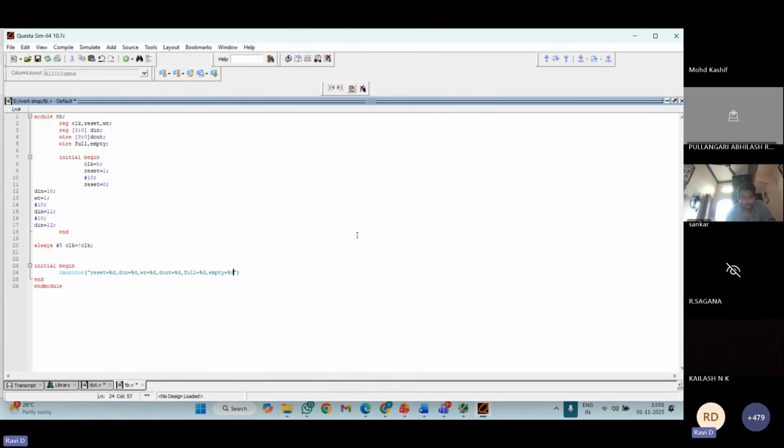So full, empty, comma, reset, din, write signal, read, full and empty. So #100 nanoseconds $finish to stop my execution. Okay.